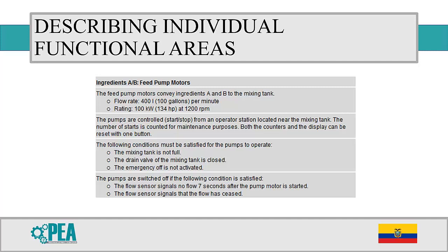Later we have the pumps that are switched off if the following conditions are satisfied. The conditions are: the flow sensor signal has no flow for 7 seconds, and the flow sensor signals that the flow has ceased. Okay, let me explain this.